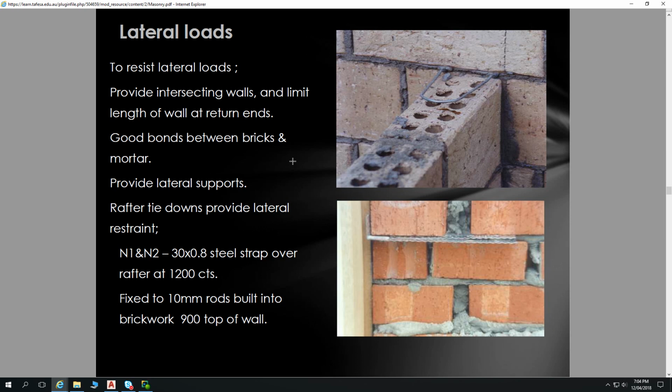Now that's how to do it retrospectively. If you're doing it while building, so we've got our brickwork. There's our bricks here, another brick there like that, and a mortar gap, and then our bricks on the other side like that one there, mortar gap. The rod, you'd probably set it in there like that and that.